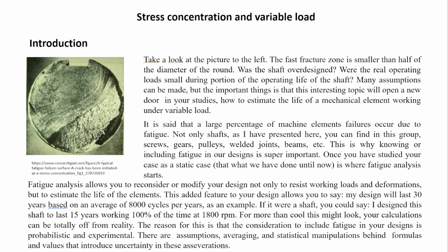This is another shaft that failed, and besides being able in most of the cases to know if a part failed due to fatigue or not, you could always assume where the fatigue failure started. For example, this is a shaft, and what you have here at the top is what is called a keyway.